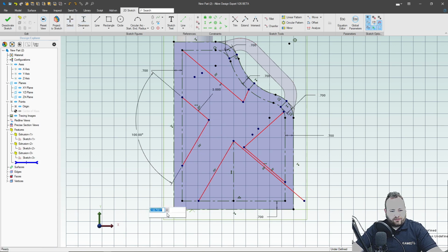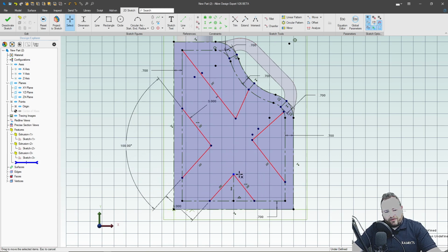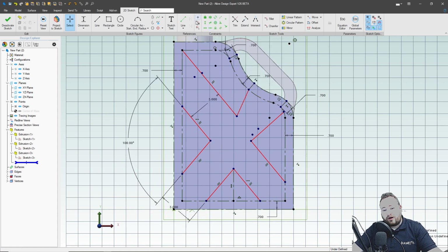Again, I'll add 3 again. That's a repeat dimension. And, you know, when you go to update these sketches, you can run into some problems if you have a whole bunch of repeat dimensions where you have to update like 3 here and then 3 there and 3 there. So you can use equal relations and other things if you're serious, so that you adjust 3, and then everything that's a dimension of 3 will update if you need to change the sketch later on. That's up to you.